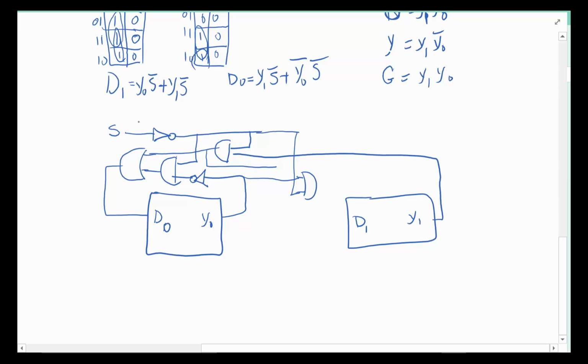Oh, I'm sorry, it's Y0. So we took the Y0, we got the S naught, we're ANDing them together. And then basically these have to be ORed together before we are done. So we're going to take this a little further out and OR them. And that gives us D1.